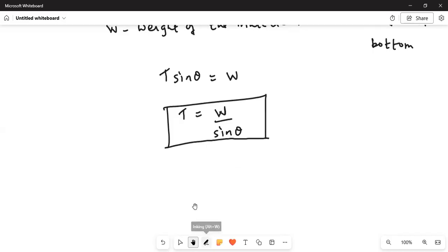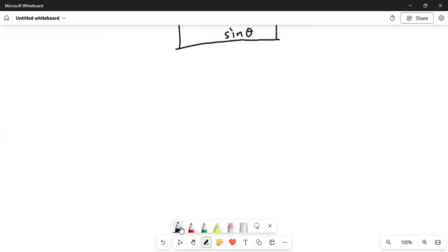Okay, next we have how to find the bending moment in the hopper bottom. To find the bending moment in hopper bottom, we need to invoke the pressure, the normal pressure. So this is your hopper bottom, which is inclined theta, and this is the normal force. I will call normal force as Pn.